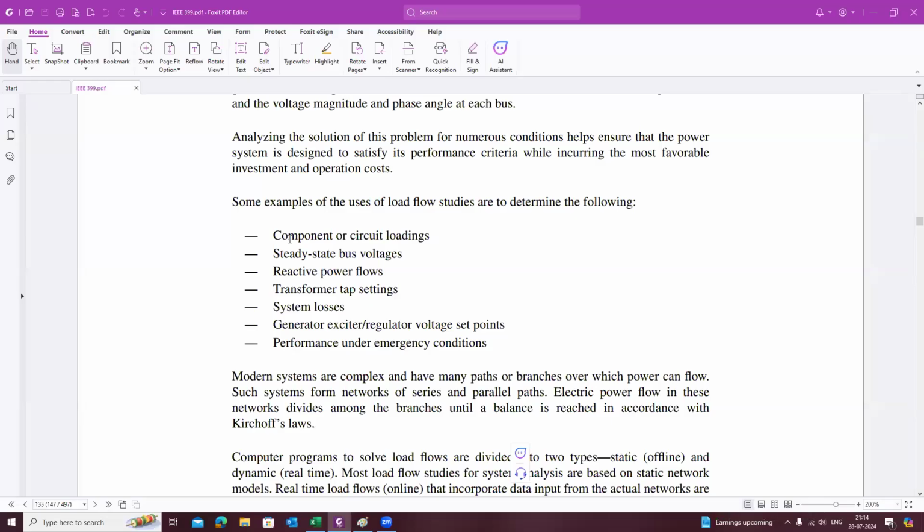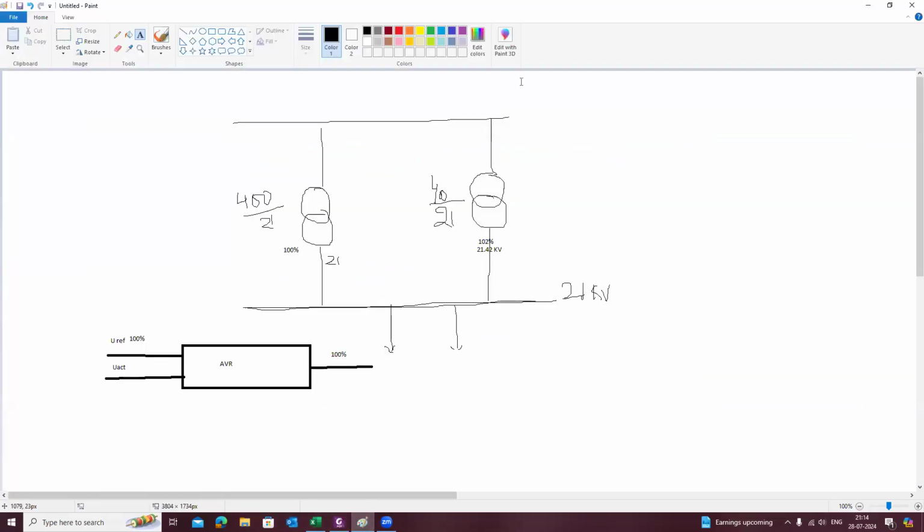Sir, why will reactive power flow be required in the system? No, I didn't get your question. So you're asking about why the loop flow? Yes, sir. Because we are paralleling the generators, at a time we need both terminal voltages to be the same, right? No, that's what I'm telling you. Harshil, right? Yes, Harshil, what I'm telling is, the loop flow will exist when you maintain different voltage set points of the generators. Okay. Yeah, sir. But is it physically possible for parallel connected generators to not have the same voltage, sir? Is it a possible thing, sir?